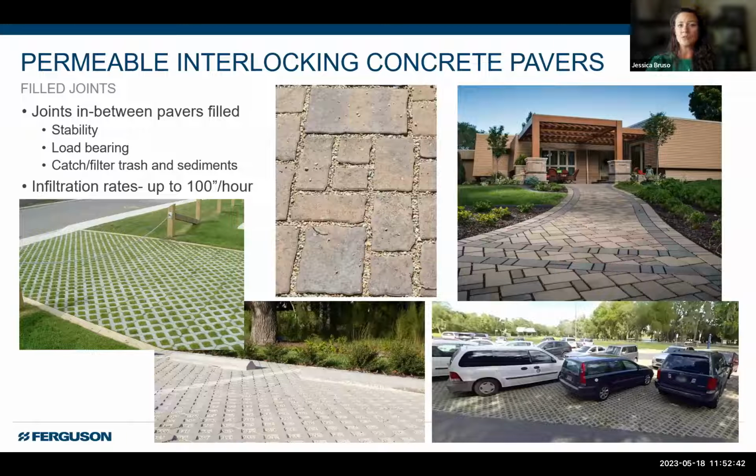So what does filling that do? Remember, it's for filtering, right? We do filter that way, but also for the pavers themselves, it provides stability and load bearing capacity, depending on how they're designed for where they're going to be. Now, infiltration rates in general for these end up being about 100 inches an hour.